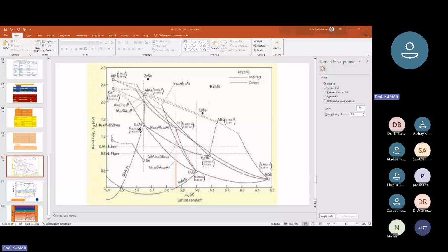One, the electron should keep on moving with a very high velocity. It should shoot out of this point here, whereas it is literally not possible, because of the conservation of momentum principle, and therefore it has to fall down, and when it reaches this maximum, the mass of the electron varies. That is called the effective mass, and that effective mass contributes to the variation in the mobility for different materials.